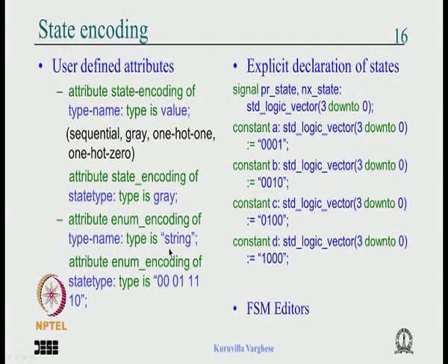And if that is not possible, you can forgo the enumerated data type and hard code the present state and next state into standard logic vectors, and you can define constants. That way, if there is a change in the state diagram and you had written numerical values in the VHDL code, you would have to change everywhere, which is error prone.